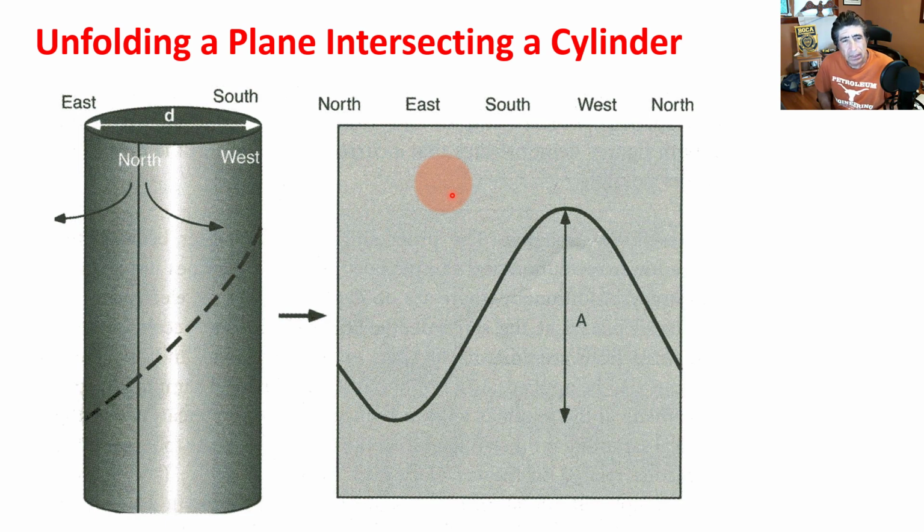But the idea is that once you cover as much as possible of the surface of the borehole, then the display that we have here is one in which we unfold the image. And so we always present the image unfolded, and to give some reference to the image, we orient it with respect to the magnetic north, east, south, and west. So we have that. And also please bear in mind that if you have the intersection of a plane,